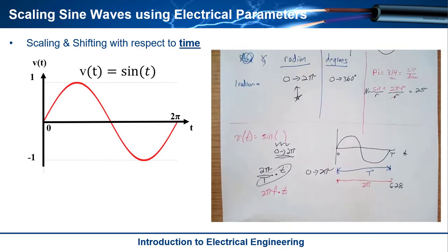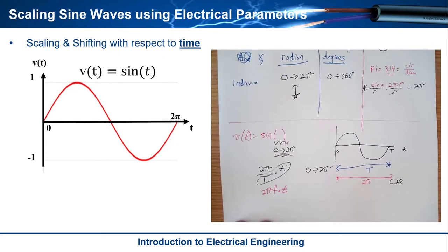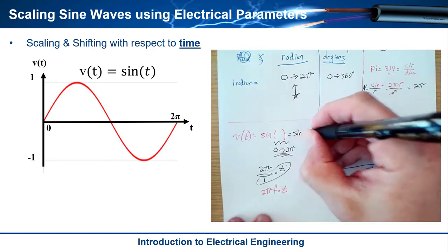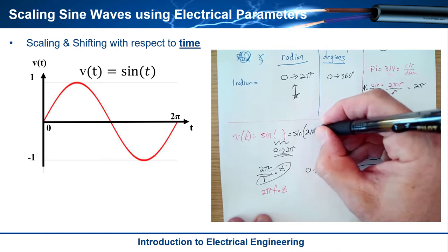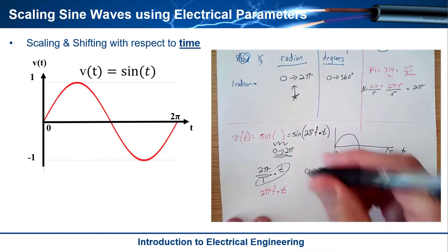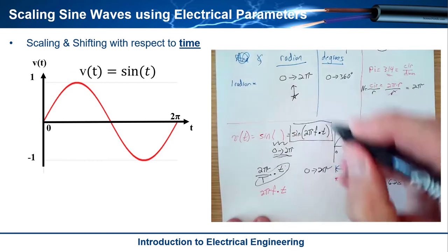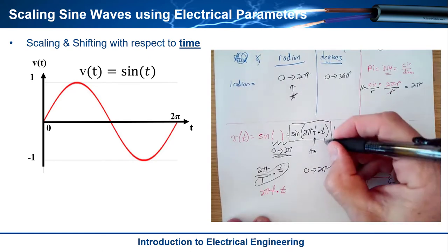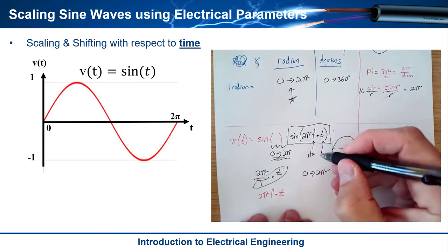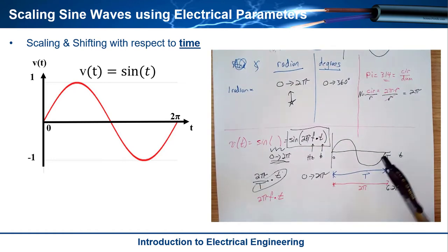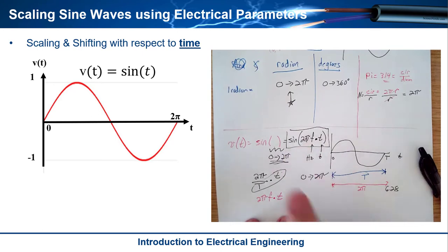And this is it. This is what we do in electrical engineering to model a sine wave. Let me rewrite it again: sine of 2 pi frequency multiplied by t. And that right there is how we define it. That allows us to use frequency given in hertz, and also time, just marching along. And as long as we apply the scaling factor, it will convert it into something that can be used in the base sine function, which is in radians.